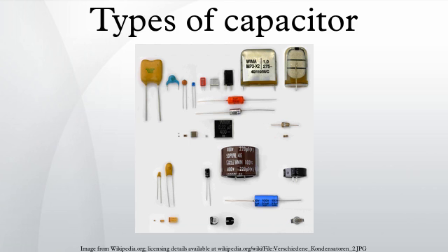Another type, the electrochemical capacitor, makes use of two other storage principles to store electric energy. In contrast to ceramic, film, and electrolytic capacitors, supercapacitors or ultracapacitors do not have a conventional dielectric. The capacitance value of an electrochemical capacitor is determined by two high-capacity storage principles. These principles are: electrostatic storage within Helmholtz double layers achieved on the phase interface between the surface of the electrodes and the electrolyte, and electrochemical storage achieved by a Faradaic electron charge transfer by specifically adsorbed ions with redox reactions.